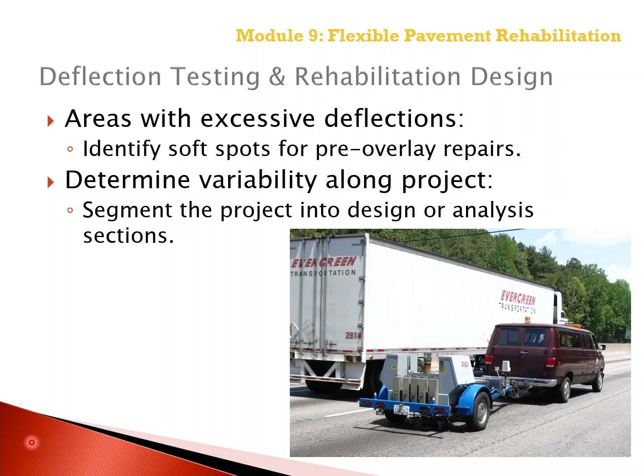If you remember from the early part of this workshop, under Module 4 on inputs, one of the key items is that the average material properties or layer properties are the inputs to the Pavement ME design software. So if we have a lot of variation along the project, this just means that it will be difficult to identify an adequate rehabilitation strategy for the entire rehab project.